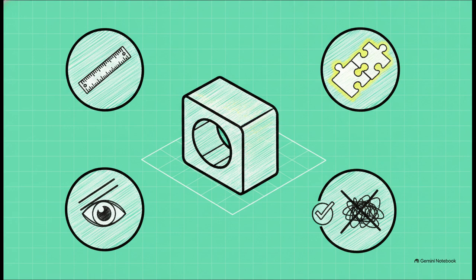This keeps things incredibly clean. Dimensions are placed for maximum clarity, and crucially, each feature is dimensioned only once. This prevents a total nightmare scenario where conflicting measurements ruin a part. Everything you need is right there, ensuring the original engineering design is perfectly preserved without needing any outside documentation.